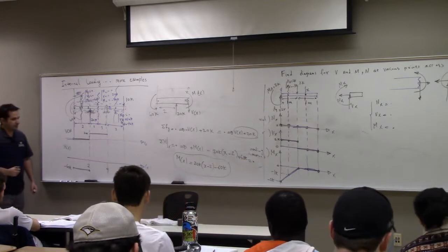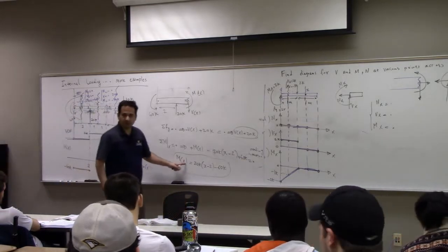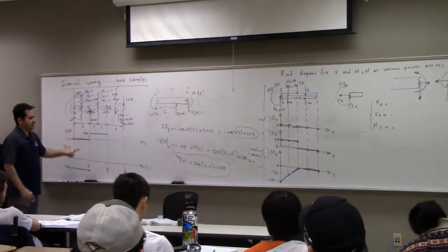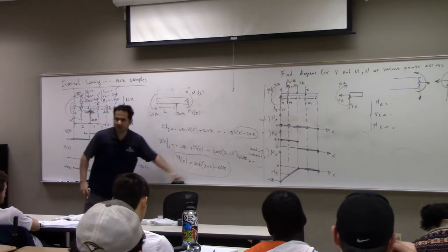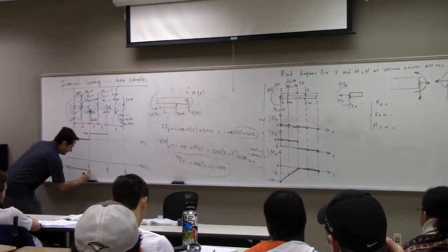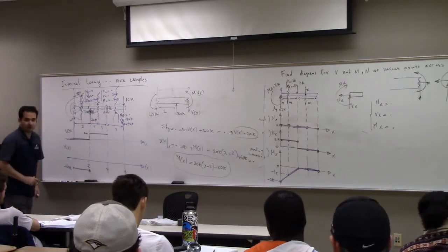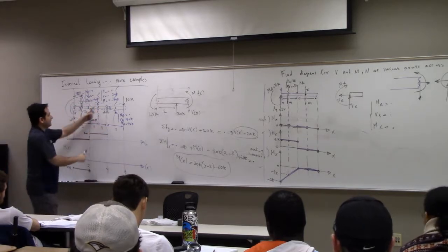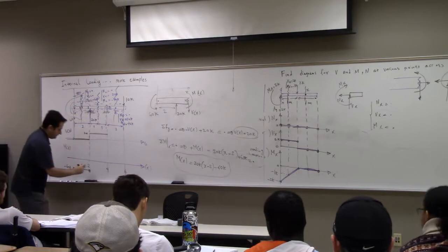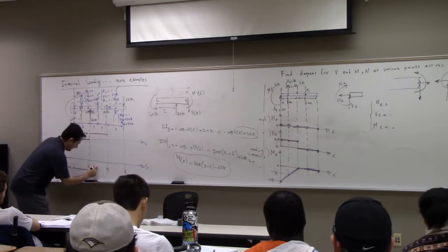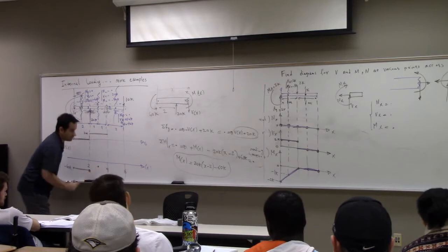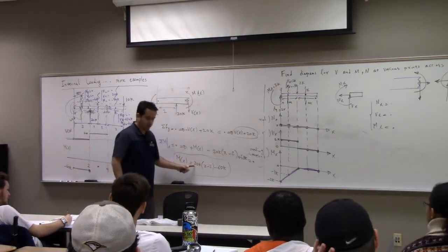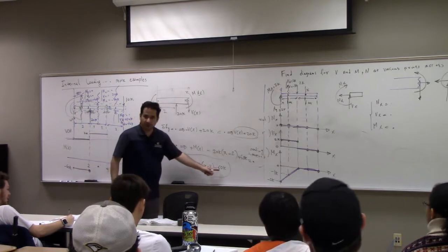Right? What about the bending moment? What's the value of bending moment at x is equal to 2 at this point? Put 2 here, negative 60. So you have this one. What's the value of the bending moment at point 3? Negative 40. And somehow you get here. Just put 3. 3 minus 2, 1 times 20, 20 minus 60, negative 40.